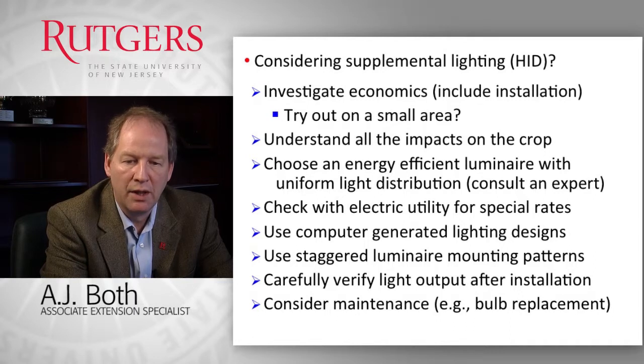You want to be able to choose an efficient luminaire. By efficient, I mean the conversion of electric energy into useful photosynthetic radiation. And so typically for that you need to consult with an expert who knows about luminaire design and luminaire operation. You want to check with your local utility company to make sure you get the best deal for the electricity that you need to operate your lighting system.